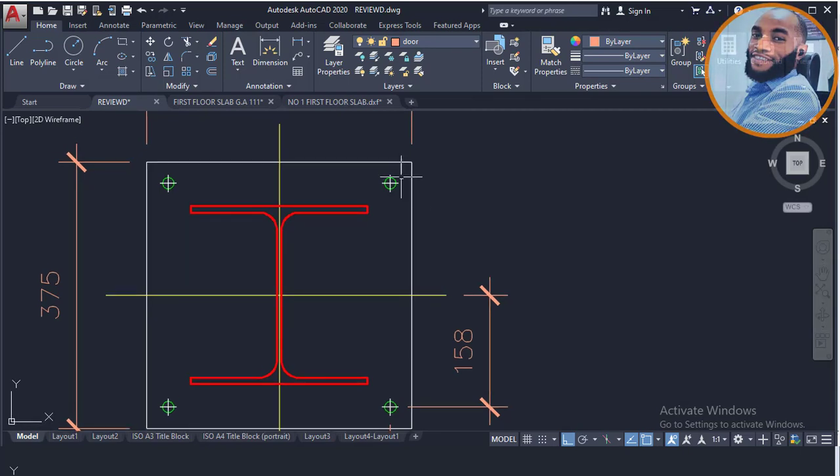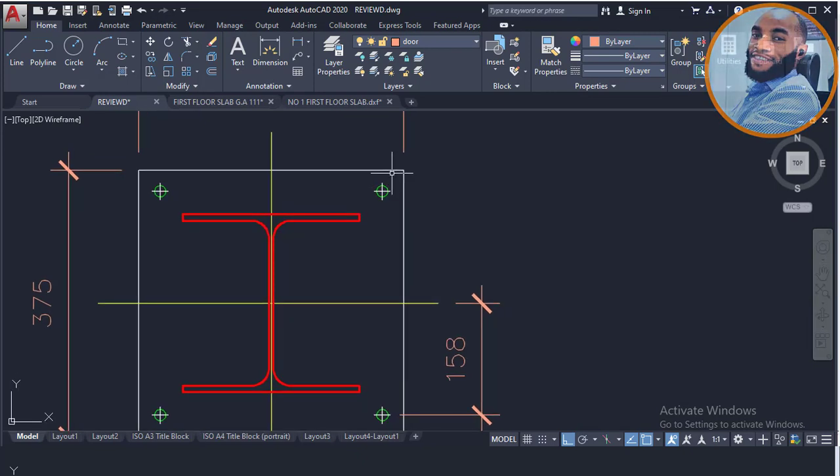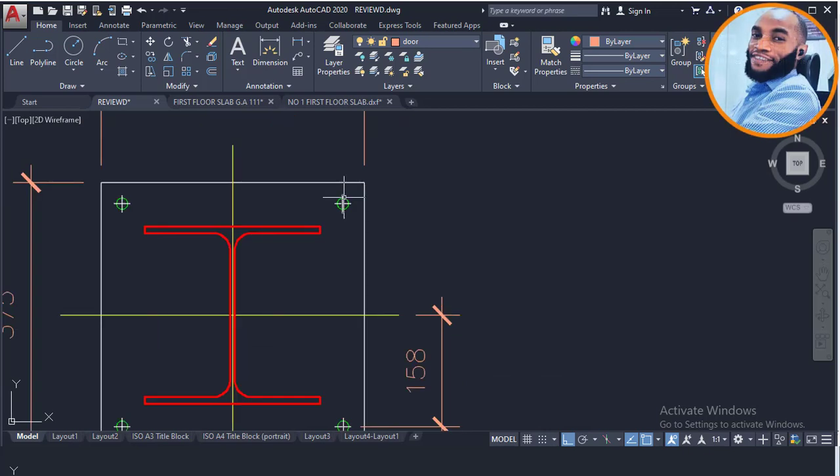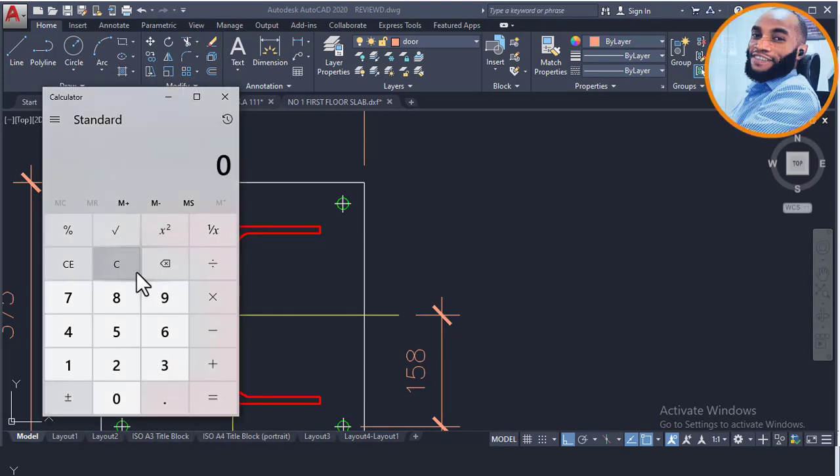Right? So there is a calculation for edge distance and also bolt-to-bolt distance. That calculation is that the minimum edge distance from the edge of the base plate to the center of the bolt is 1.5 multiplied by the bolt diameter. Now in this case, I want to assume my bolt diameter to be M16. So I want to use a bolt diameter of M16 for this steel stanchion. Since I've assumed M16, I will now calculate the minimum edge distance for that bolt size. Since I chose M16, and the formula says 1.5 multiplied by the diameter of the bolt, 1.5 multiplied by 16 gives me what?